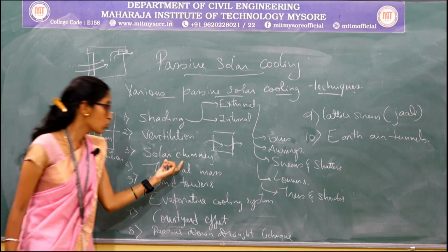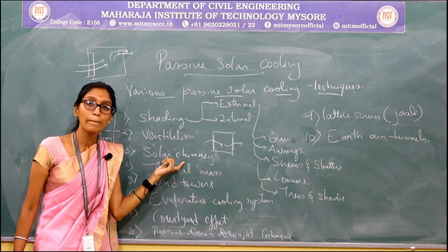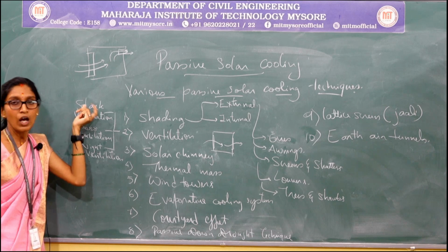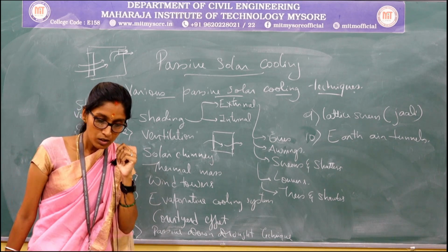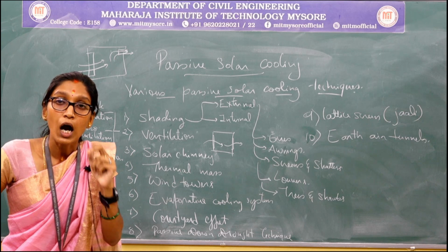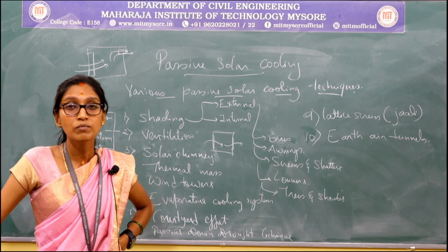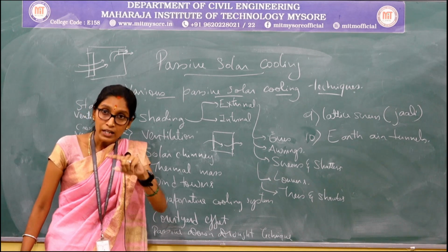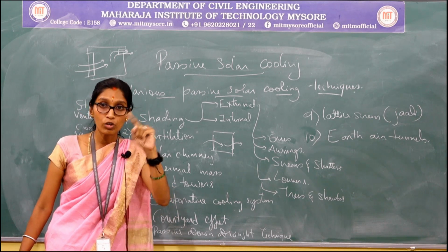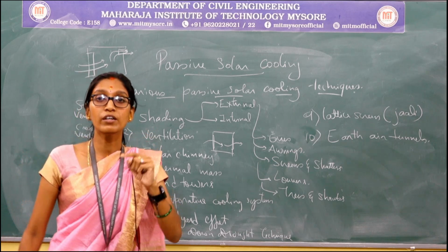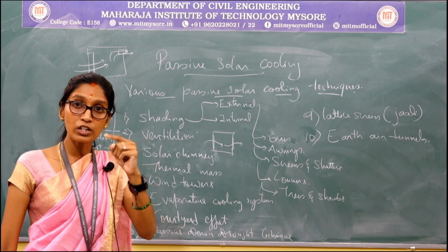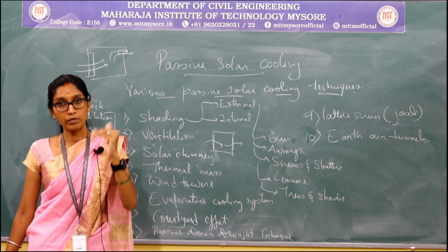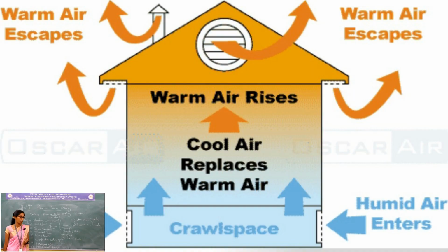So, the solar chimney works majorly on the principle of your stack ventilation. What was the principle, or how was your stack ventilation working? Yes, so it was based upon the temperature difference, right. It was based upon the temperature difference or the air pressure that is going to be developed, or we can even say that it is due to the thermal buoyancy which is going to take place.